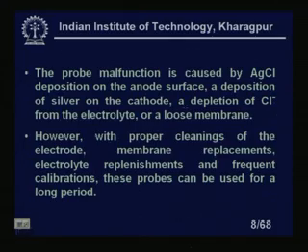This is, I should say, a very obvious thing: any sensors we use need frequent calibrations. Any probe, whether it measures pH, conductivity or dissolved oxygen concentration, will have this type of deposition.